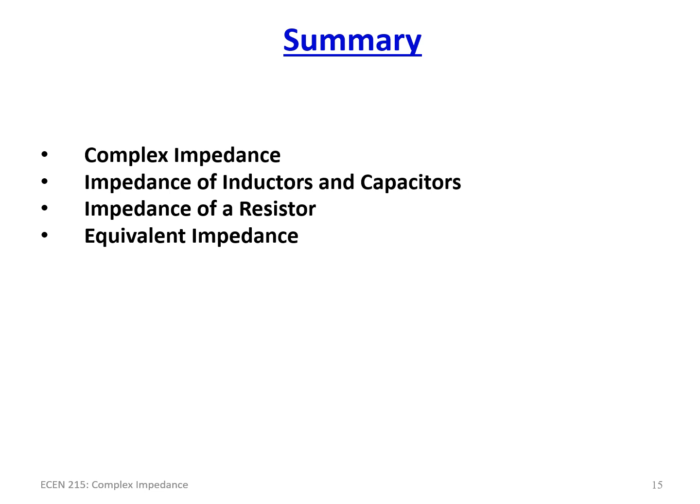and so on, up to 1 over Rn. So you have n components in parallel. That's the formula you would apply. In the case of two impedances in parallel, you would have, and of course I was using R, it should be Z, Z1 times Z2 divided by Z1 plus Z2. So you're effectively changing R for Z. It all effectively means the same thing, just now you're using phasor arithmetic.